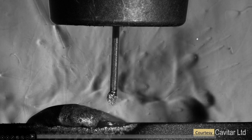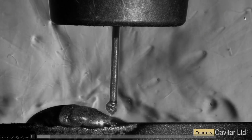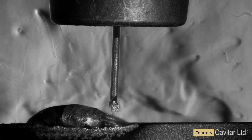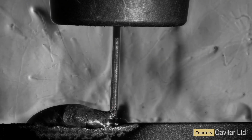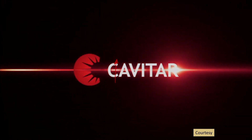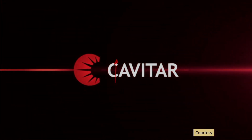This is a typical video of how the CMT works. The slow motion of the CMT process can be seen in this video. Here we can see that when the short circuit happens, the wire goes back. It is pulled back by a mechanism, and as a result it leaves the droplet behind. So this is basically how the CMT works.